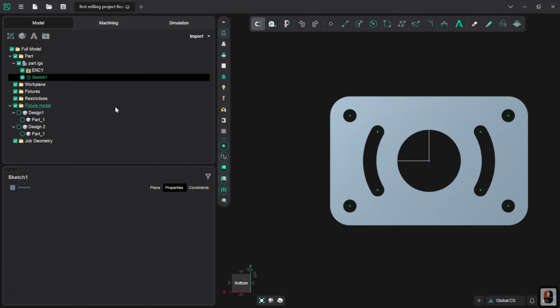So we're going to go to the arc tool and go with arc with center, first point and angle. We click on this, and with Smart Snap turned on, we make sure that we snap onto the center point here, to the top, and then bring it round to the 90-degree point. And we're going to do the same for each of these.